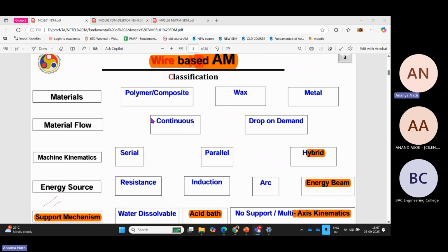In case of wire-based AM, if you're talking about plastics, then you will get a melt pool, but it's not fully liquid because its viscosity is higher. It will be kind of like toothpaste, a semi-solid or semi-liquid state. But when you're talking about a wire, the process is the same, but it's more liquidy.